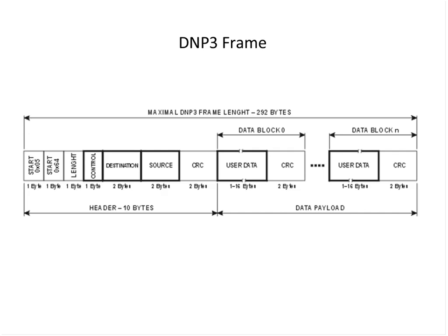Here is a typical DNP3 frame. This frame shows you a header and the basic stuff that involves the source and destination address and the length of the packet and the start. All of those things are there. And then there is the payload. And in the payload, there is information about turning something on, turning something off, requesting some information, or the remote device spontaneously is providing that information.